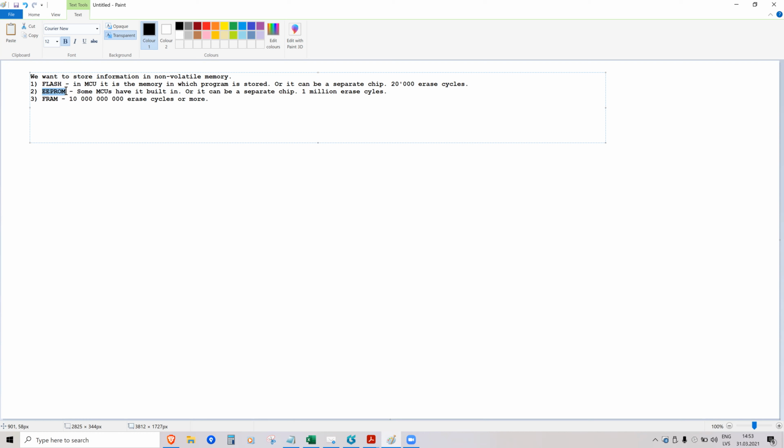So oftentimes these devices can be fixed just by replacing this EEPROM chip. You disassemble the machine, you find the EEPROM, desolder it, buy a new one on the internet, solder it back, and it just magically starts to work. And also, this problem appears in cars and in some trucks, which also store settings in EEPROM, and you switch on the car and its dash works strangely or something like that.